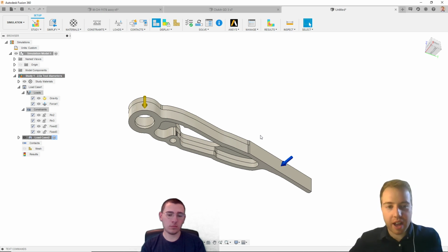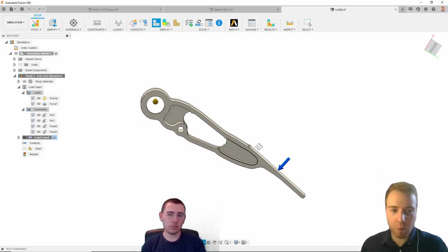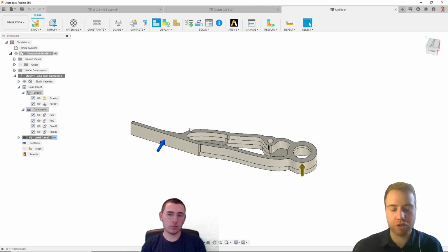This is, again, something I'd recommend when you're using generative design and you're trying to create high performing components. I would always recommend to people, once you've downloaded the outcome, bring it back into Fusion and run it through simulation. That's just going to give you so much more information about how this performs under your load conditions beyond what you just get in generative design.